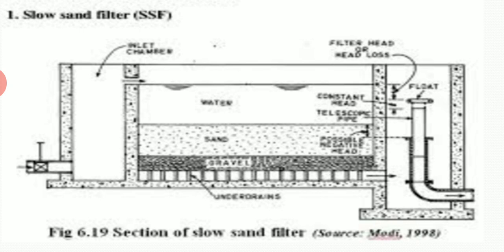Here you should know something about uniformity coefficient. The uniformity coefficient is defined as D60 to D10. D10 represents the size of particles in mm such that 10% of the particles are finer than this size. Similarly, D60 is the size such that 60% of the sand particles by total weight are finer.